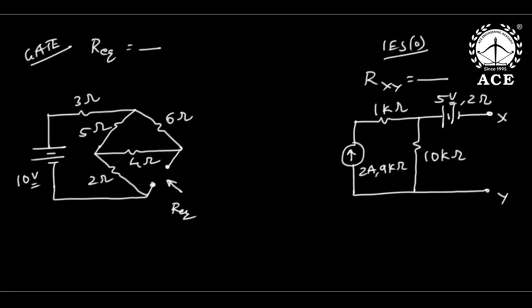Yes, everybody see here, I need R equivalent. Now this is a simple observation bit, sir. Left bit is an observation bit. Because I want resistance, I can remove the voltage source. Yes or no, I can remove the voltage source. So if I remove the voltage source, watch this, I'm shorting. Remaining things I'm writing again.